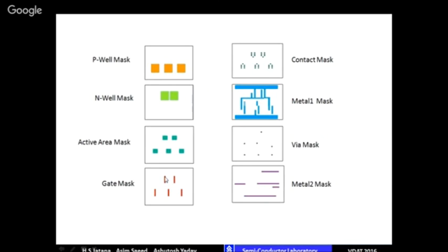This is the polysilicon line, and below this will be the GOX, gate oxide, and then both sides will be diffusion masks. The diffusions are not shown here, but you can take this line and put it on here exactly. The other side of this line will be the source drain diffusion. So this is how the active area comes, and on top of it is the gate mask.